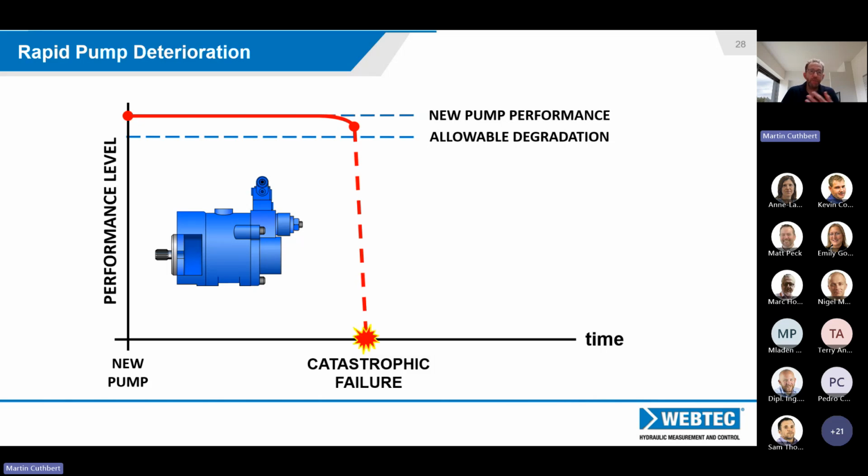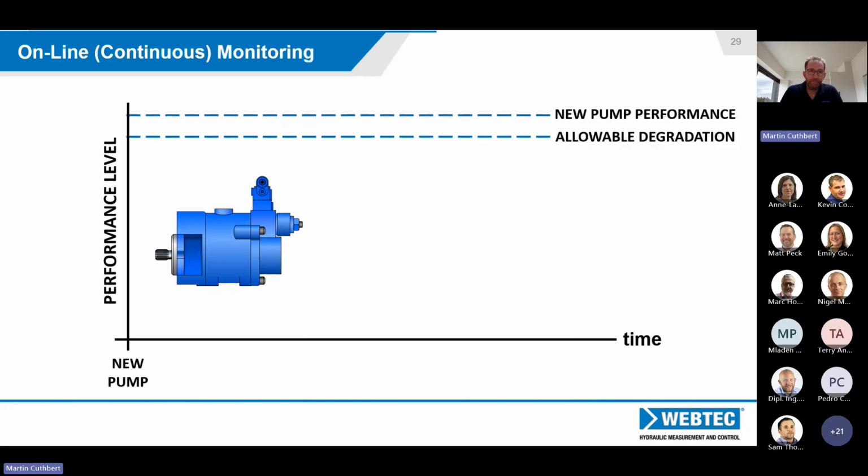So from a condition monitoring point of view, you've got a couple of different options here. Had you installed the CTA and connected it straight into the PLC, you could have that data feeding in continuously, in which case you could see everything every second that was going on with that pump. That may or may not be that easy if it's a retrofit. If you're carrying out the testing periodically every 6 months, there's a chance you might miss it in between those 6 months, but equally that may be sufficient for you to see the trends on the pump, and see what's happening, and what's likely to happen in the next 6 months.